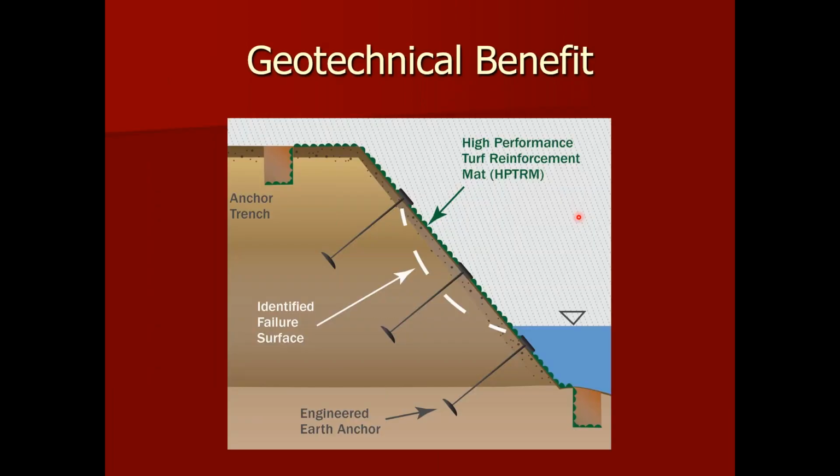As I said, the geotechnical benefits are pretty well understood. There's a lot of empirical relationships and software packages that will allow us to determine what that failure cone is going to be, the depth of anchor, the spacing of anchor, and how geotechnically, with steep slopes or even with channel restoration for pop out and saturation failures, to sandwich those layers together to ensure the geotechnical stability.